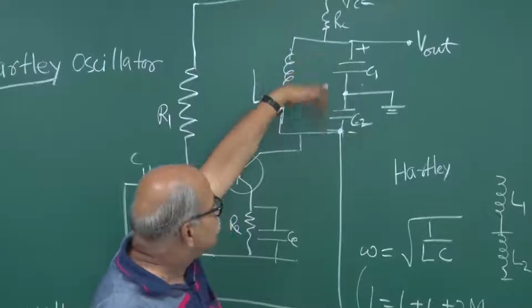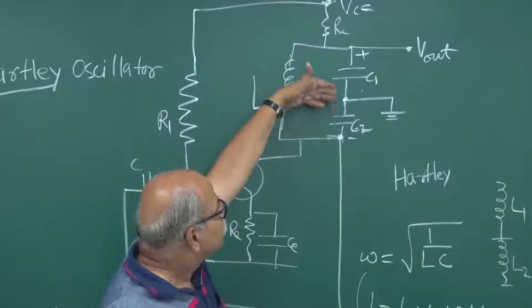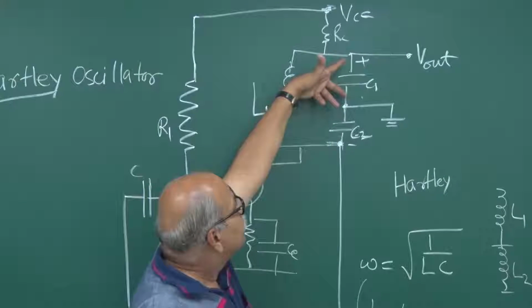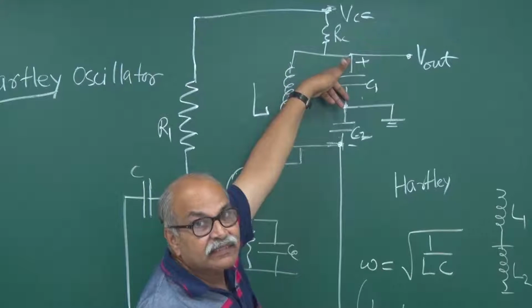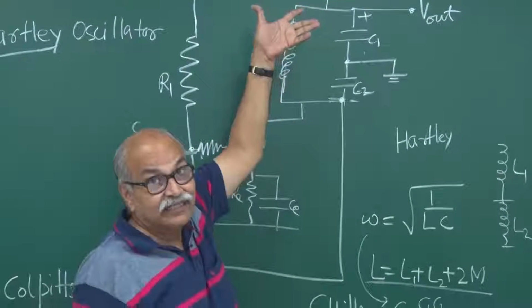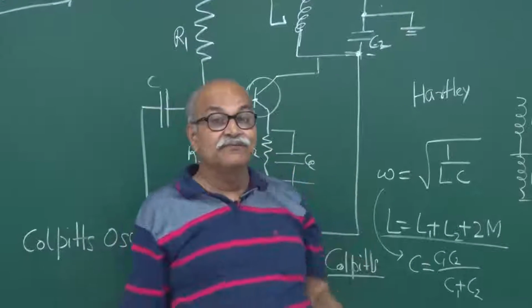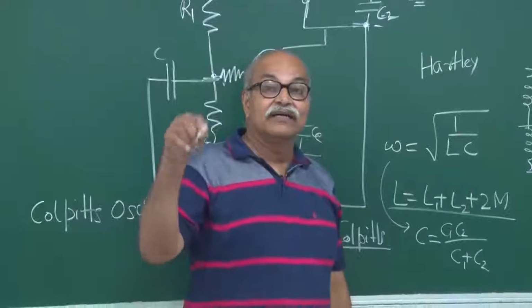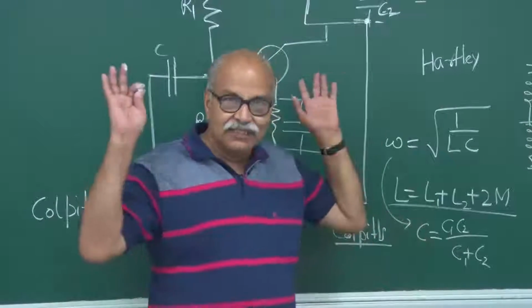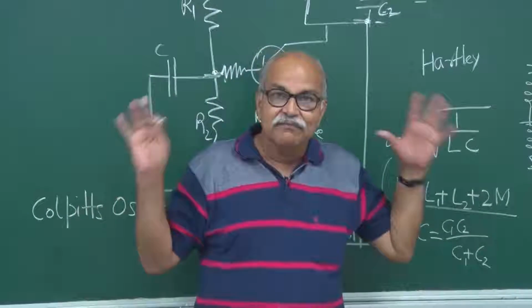Once again they are series connections, so depending on what the reactances are, that fraction of voltage will be here and that fraction of voltage will be there. These are all AC things that we are talking about. Okay, so when you use 1 over C omega, L omega, those things will be operative. So this is how the oscillators are generally made.